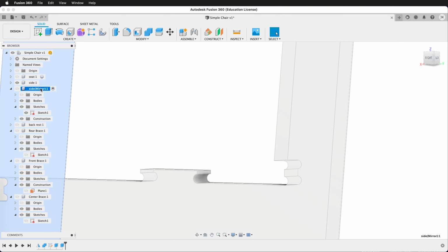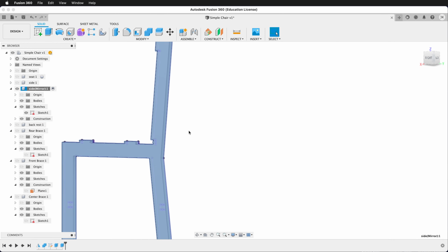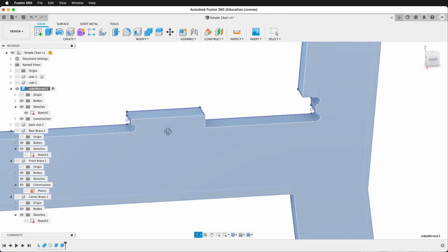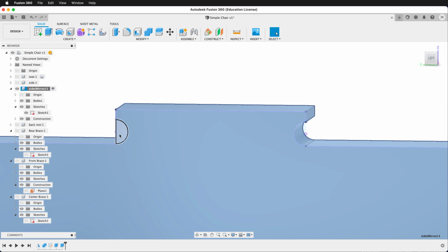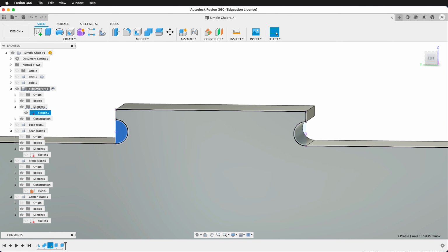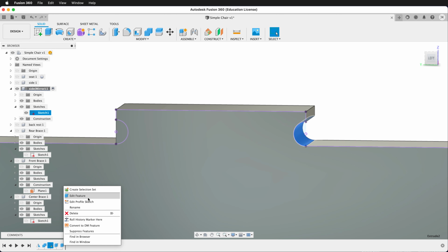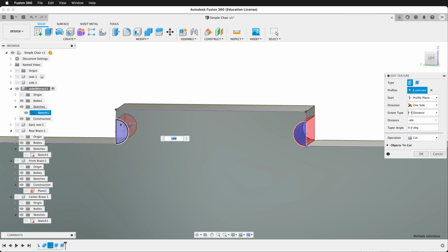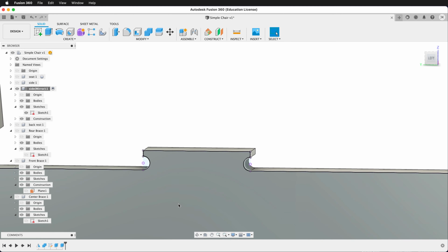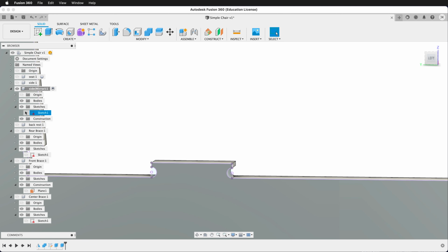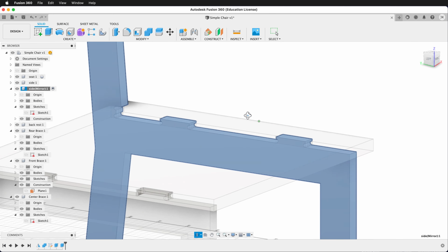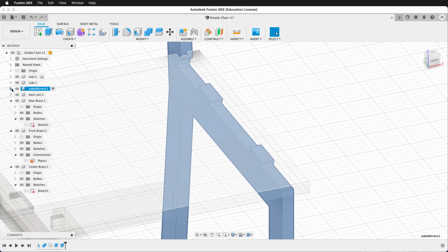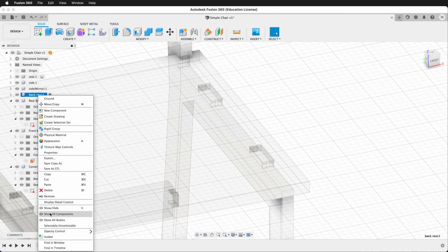Then I activate side mirror and then isolate it. And that projection comes through. So this is the good thing about parametric modeling: I can now edit this feature and have the same thing happen. So I'll add that piece in, and then everything will be fine. So now I can hide that sketch. I can unisolate side mirror, and we'll continue moving down our browser, adding fillets. So let's go ahead and activate the backrest, and then I'll isolate it.